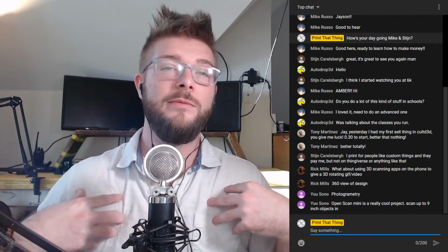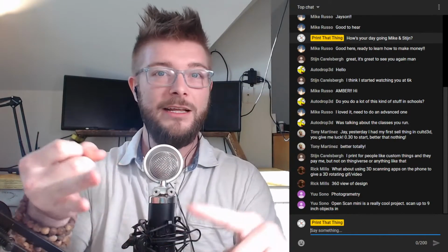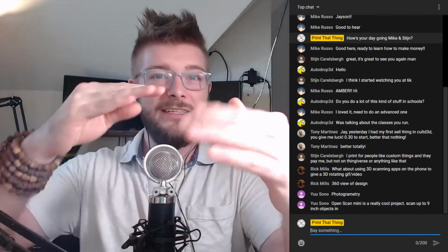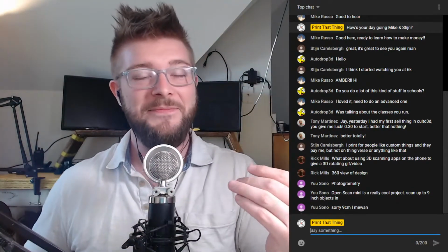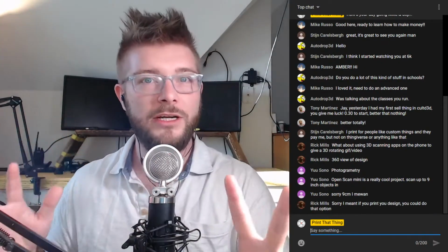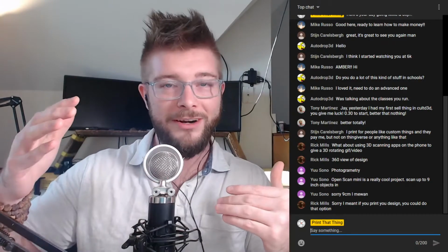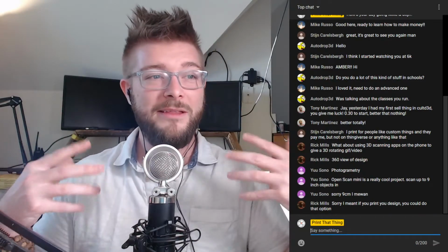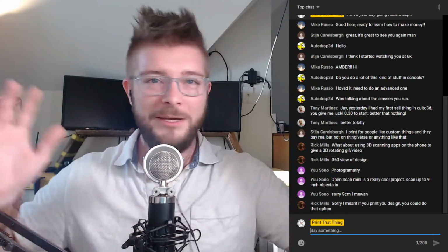But that's something that I need to personally work on, writing what types of materials work best, what type of slicer settings, uploading your slicer settings, your shells, your rafts, all the details, anything someone could possibly use for their 3D print when they're 3D printing your design. Think of this as the customer experience or the user experience for your designs. The better you are at this, the more likely they're probably going to tip you. We'll get to maybe how they're going to tip you in the next tip. Tips on tips on tips today.